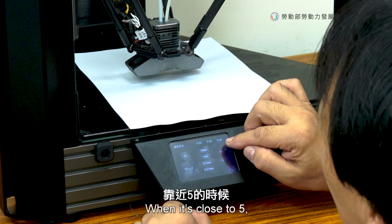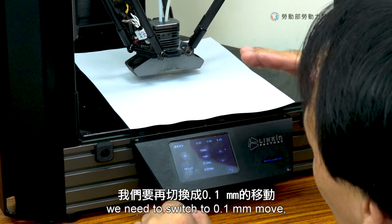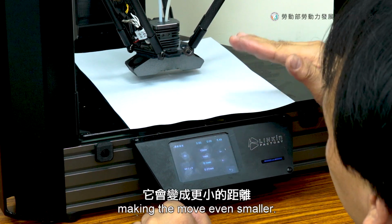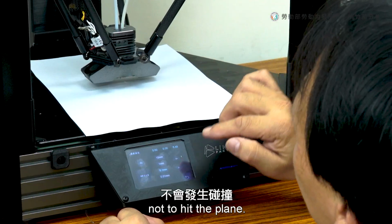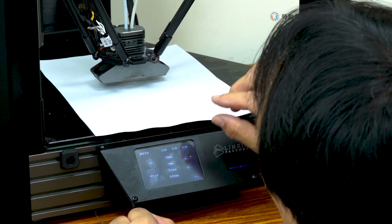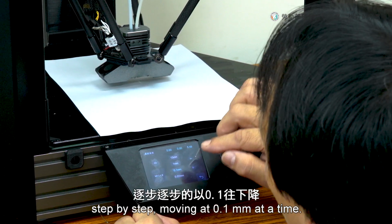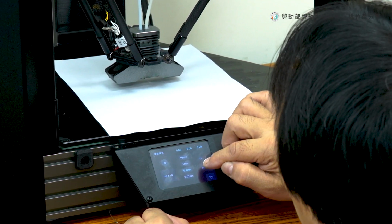When it's close to 5, now it's 6.49, we need to switch to 0.1 millimeter move, making the move even smaller. This will ensure the nozzle does not hit the plane. Okay, we move from 6.49 down step by step, moving at 0.1 millimeter at a time.